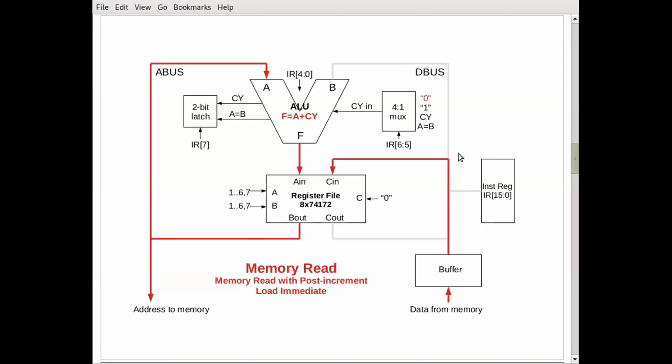And this actually is the tiny little bit of onboard hardware that isn't being done by micro instruction bits. Arguably, it should have had 17 bits of micro instruction because there's two different functions being used here. One is the store function for the instruction register. The other one is the store function for the R7 in the register file. So I cheated to the extent of 1 bit.